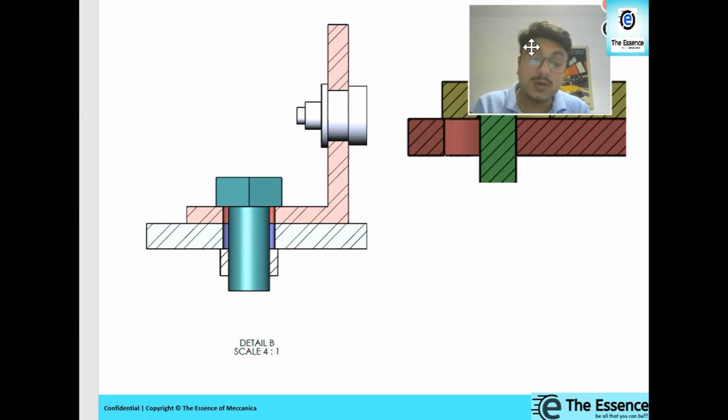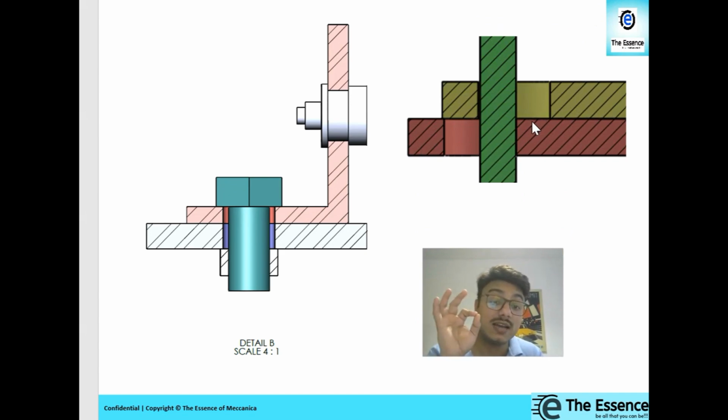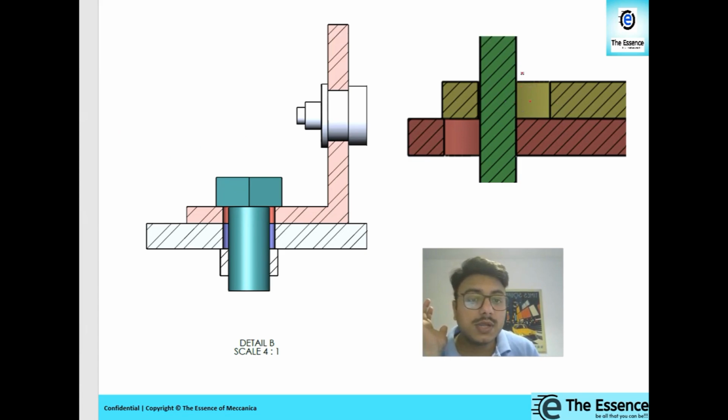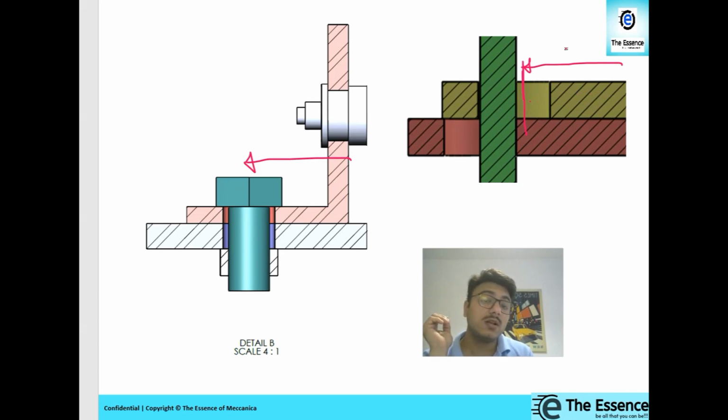Instead of calculating plus or minus 1.3, you can directly consider those diameters in the tolerance stack up analysis. How to do that? In case of doing it, we reach from the L bracket till there, right? From there to the center of the hole we can reach, right? That dimension is available. From the center of the hole, considering the diameter of the clearance hole on the L bracket, I can reach this edge over here, right? So that will be another dimension in the loop.